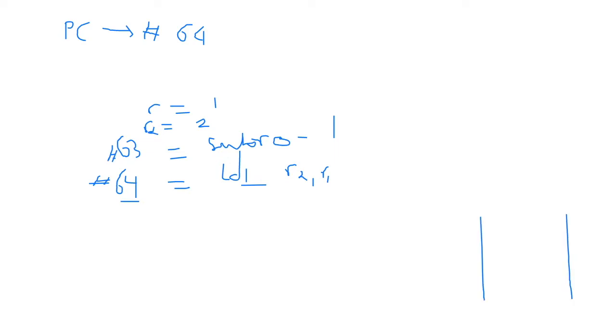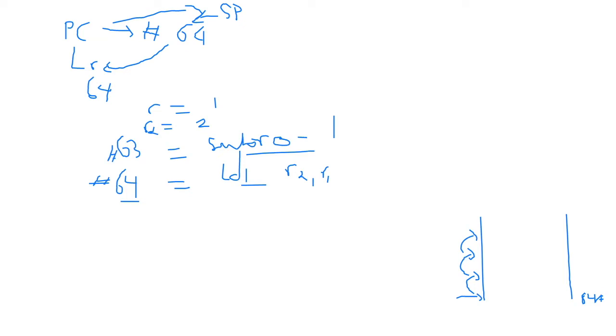So normally there is a register called the link register. It will push this 64 onto that link register and make room for the new address. So let's say in this case it went into address 84F, for example. So it will push the address of the stack pointer onto the program counter. The stack pointer will point to this address, and you'll go into the subroutine to execute it. Then when it finishes, it goes to the next one, and the stack pointer will increase, goes to the next one, until that subroutine is finished.